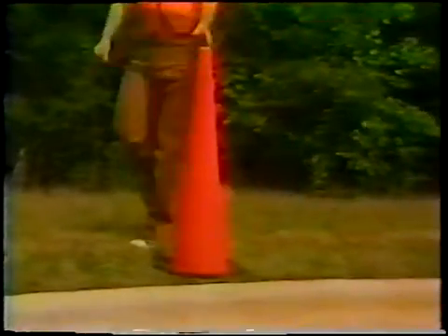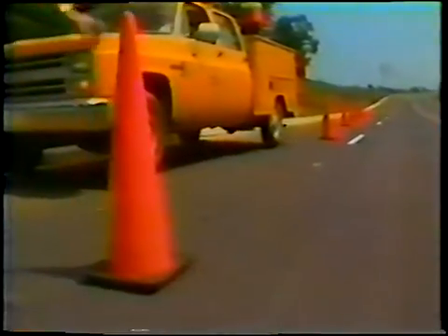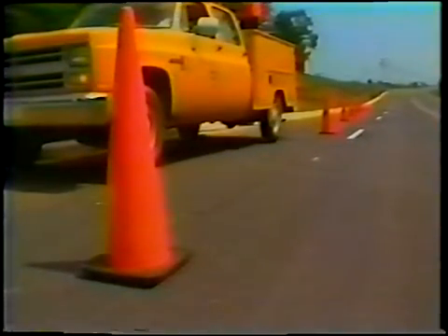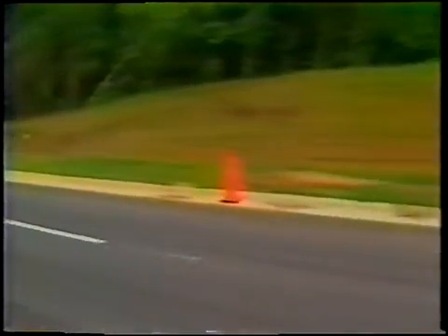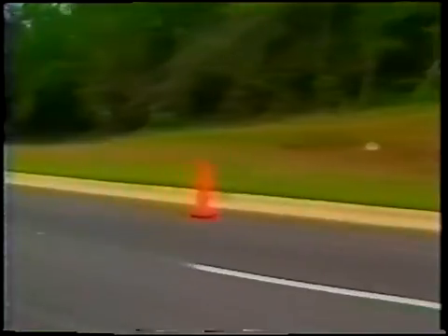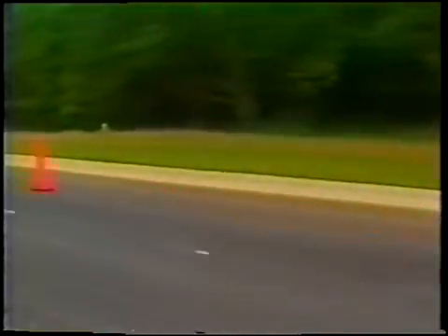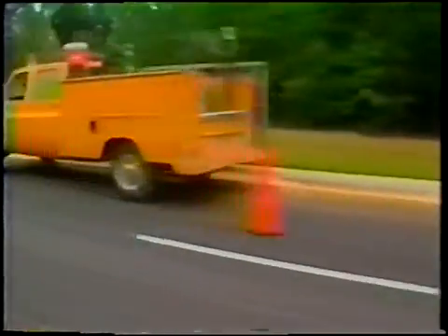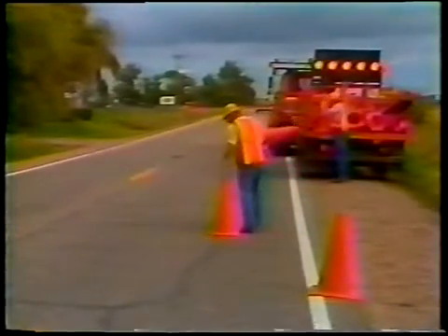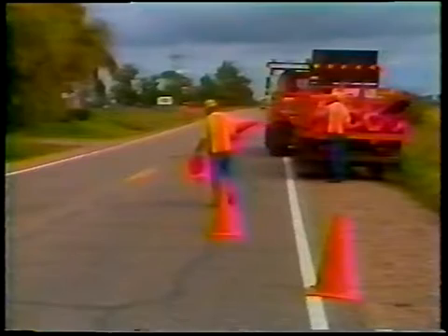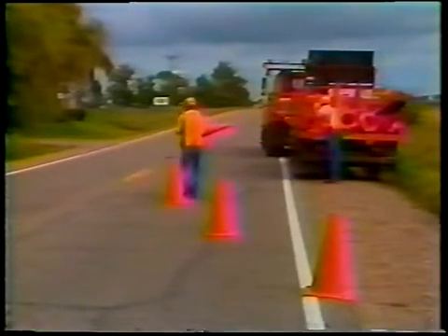The transition area should be obvious to drivers. The correct path should be clearly marked with channelizing devices so the drivers will not make a mistake and follow the old path. If the existing pavement markings create confusion, temporary markings should be used. A taper is a series of channelizing devices placed at an angle to move traffic out of its normal path.